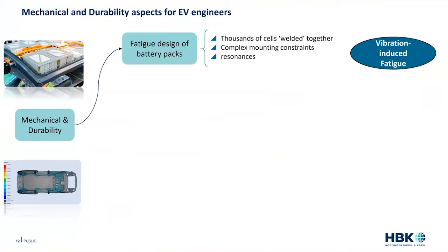But also the combination of lightweight support structures with the heavy batteries results in mechanical resonances, which themselves lead to fatigue failures. So here we want to run some CAE-based vibration fatigue to optimize the mechanical parts for life, weight, and cost in general. So that's one aspect we'll cover in this presentation.